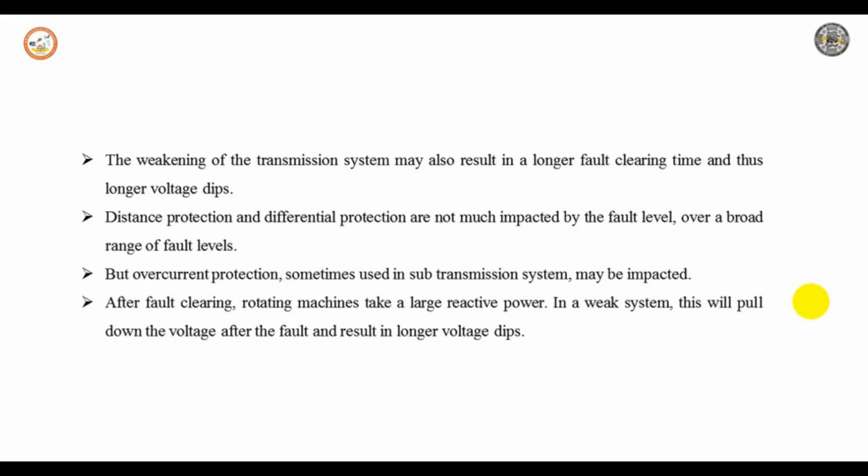So here we enter a real-life transmission system, where the impact depends very strongly on the system. The power electronic converters with which many distributed generators are equipped can be used to maintain the voltage for the local load. Here two different approaches are discussed: temporary islanding operation of the generator with a local load, and the injection of reactive power during the dip while remaining connected to the grid. More detail about these different algorithms is discussed under the voltage dip topic.